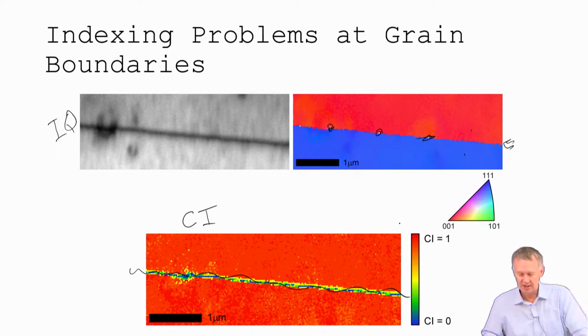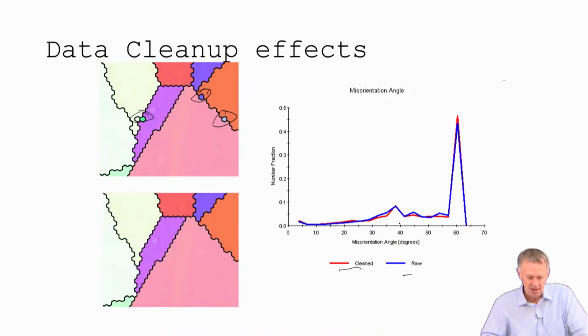All right. The other thing it could be is some kind of pitting, some kind of etch pitting, which you get a really strong contrast. If your beam goes down into a pit, you get a strong contrast with that. And sometimes that strong contrast will give you the same orientation everywhere. So if there's pits along the boundary from the polish that you've done, then you might see something like that. That's another thing that it could be. Okay. But this is something I tell people to do for boundary statistics, but I also say be really careful because you're just inventing data, right?